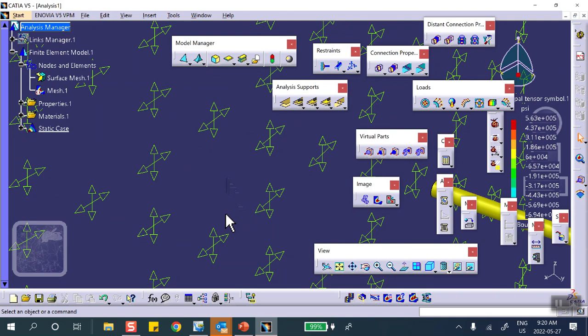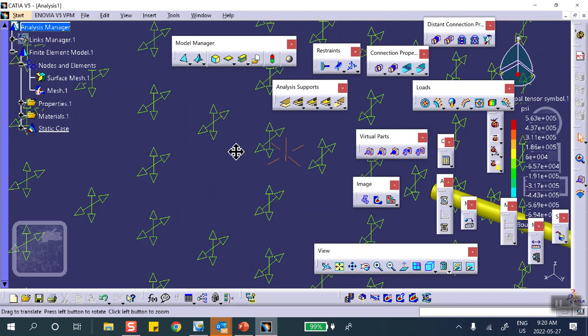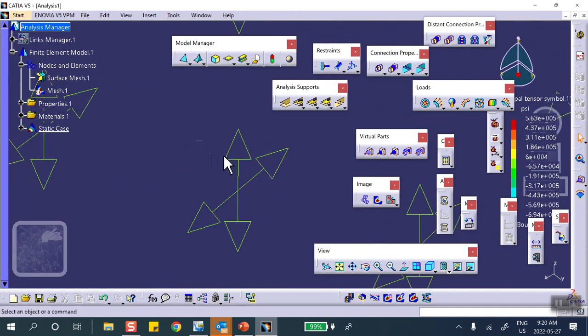Principal stresses, and in fact, these values are PR over T and PR over 2T. If you zoom in closely, you see one of them is double the other one. Yeah, see that? The hoop stress is double the other one. You multiply 5 by 2, you get 10.